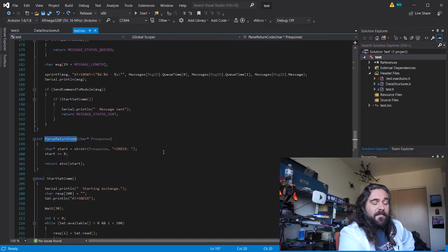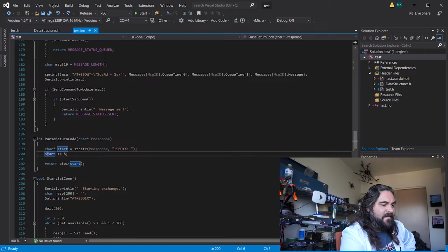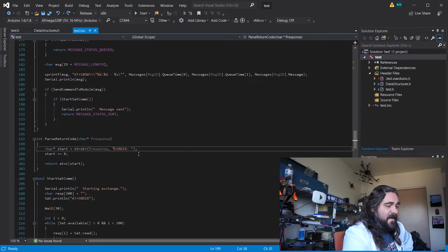If you're unfamiliar, you can look at the other video that I did where I go more in depth with that particular operation. So what we're doing is we're looking for the start character. In strstr, we're processing the response that was sent to us, looking for plus SBDIX. Anything else that it sent, I don't care about. I want to get to the start of here. Right, and then we take the start and we add 8 characters. Why 8? Because 1, 2, 3, 4, 5, 6, 7. Right, so we want to move 8 characters into the message so that we get to the actual first digit of the first number of the response. And then we return atoi.